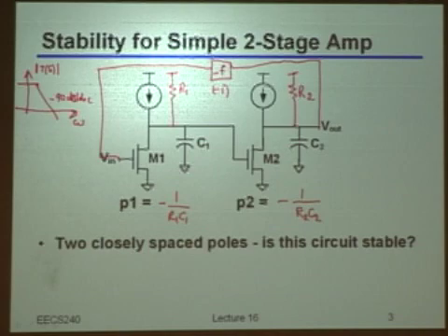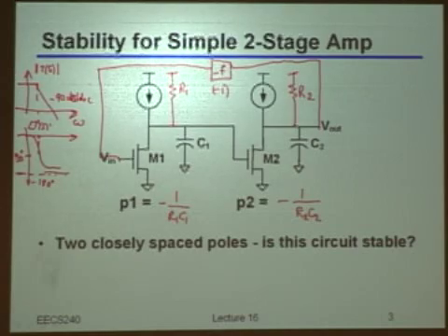And what about the angle, the phase plot? The angle of T of S. So I would also have basically a phase shift of minus 90 at the two poles, where the two poles are, and then something like that. And asymptotically, I would reach minus 180 degrees. So here we are now.